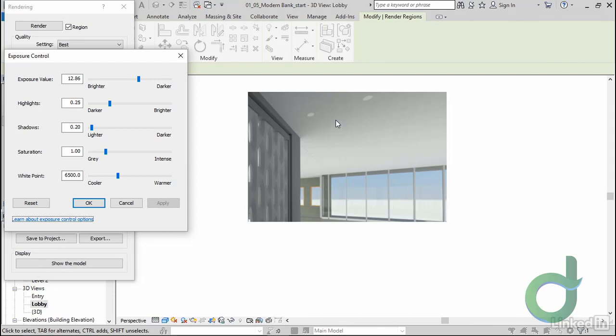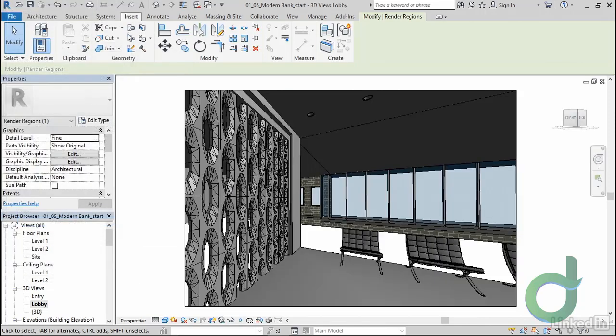It's working nicely. Now bear in mind I haven't done anything to really touch up the lighting other than put stuff in and deal with the default sun. But in a typical situation where this is lit largely by bounced light, my ceiling, even with all these holes cut in it, is behaving well. If you'd like, you can add in more can lights. I'm going to stick with the 5 I've got here as kind of an accent over this wall, and then later we can add in pendant fixtures if we need.